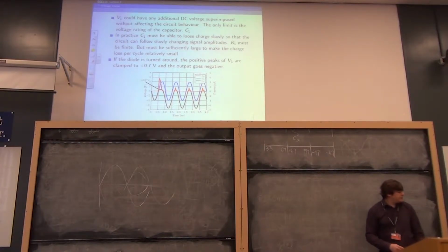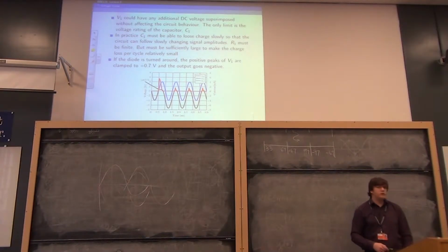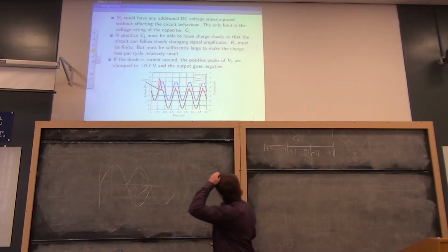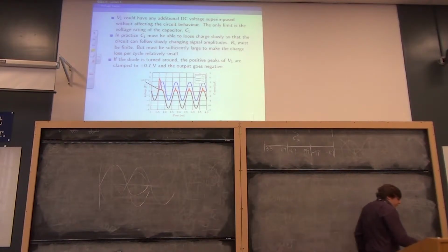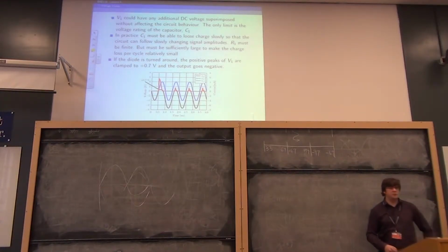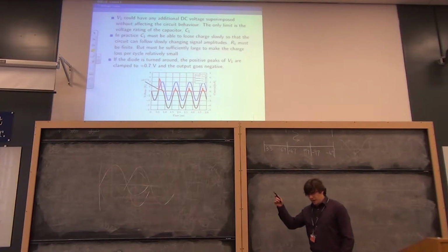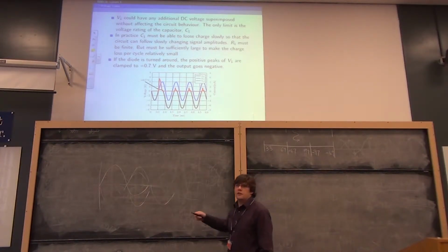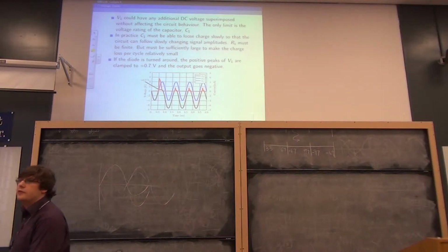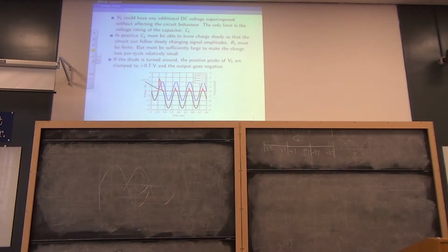And you could add any additional voltage you wished. So you can have V1, which I had as 4 sine omega t plus 5, where 5 was 0. If I wanted to have 4 sine omega t plus phi, all in brackets, plus 10, that would be fine. So you can add the DC if you wish. It makes no difference to how it works.